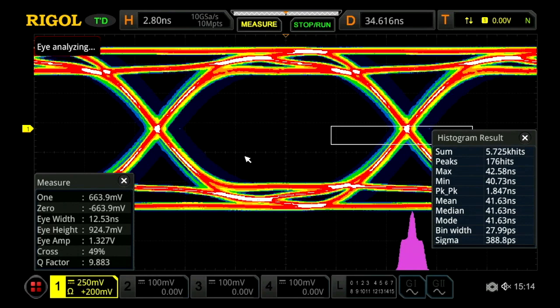Now that we've identified the issues in this eye diagram, we went ahead and started to debug the problem. The first problem we found was the signal that was causing the amplitude noise. So we've been able to remove that, isolate that crosstalk, get rid of it, and reduce our noise on all of these signals. So now we can see how these signals are separated, the top layers, and we're starting to open the eye a little bit.